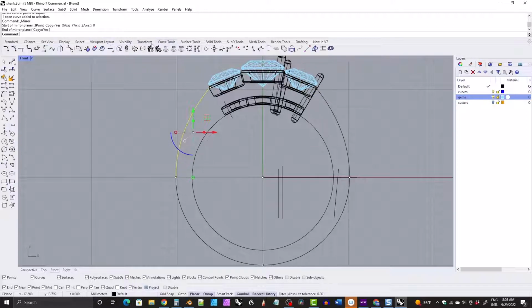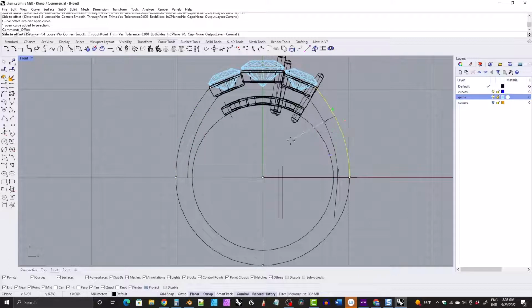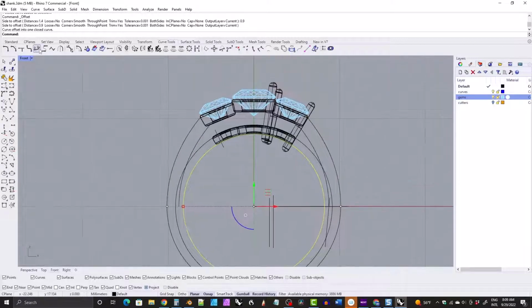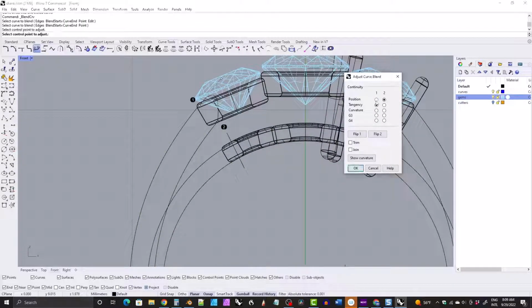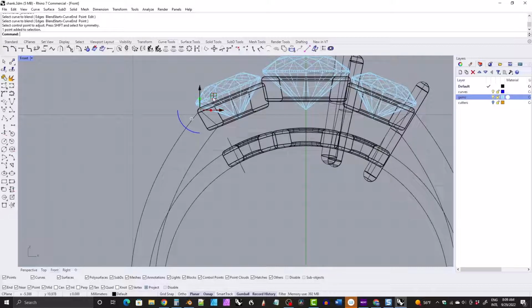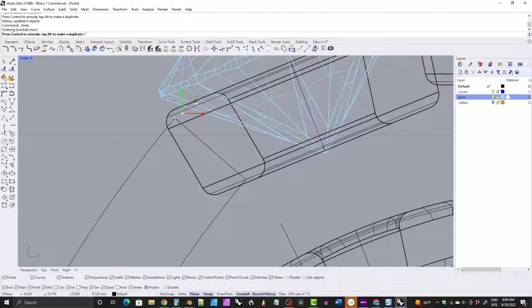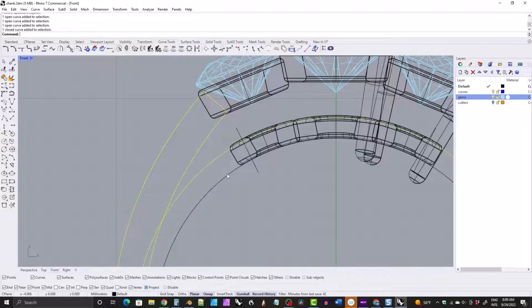and we'll offset that by 1.4, and this one as well, and we'll offset this by 0.9, and then we will blend the ends of these two curves together using position, and then we can change this around like that. So we just need to pull this in a little further this way, and that's probably going to be fine right there. So we'll try this again.